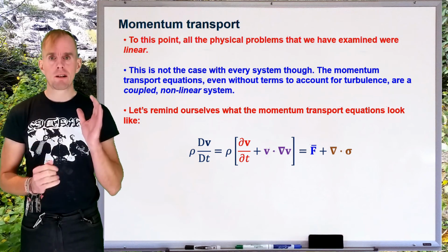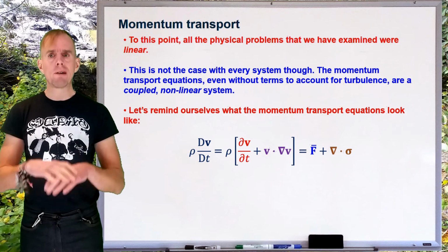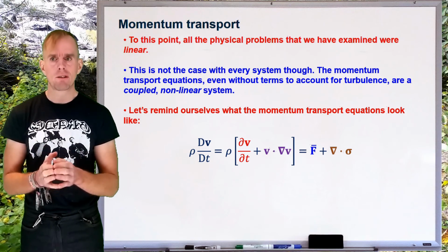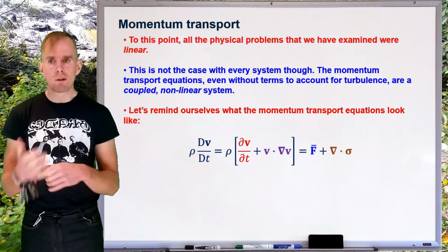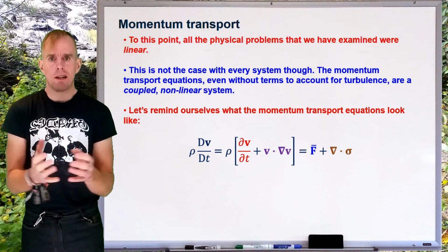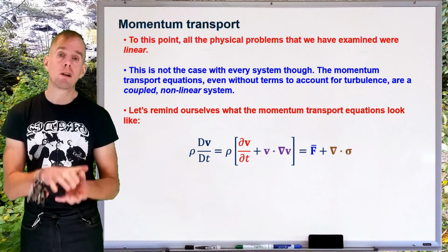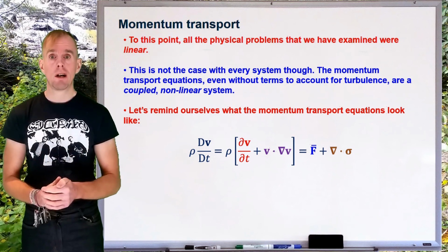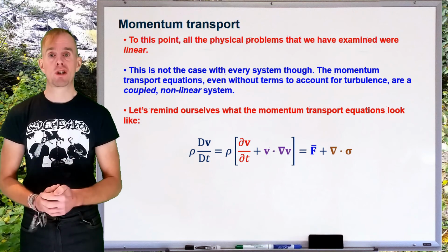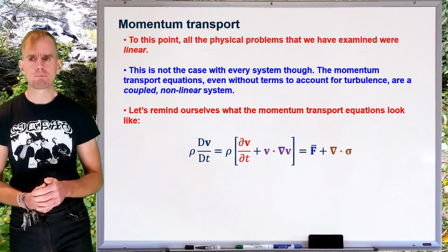And then we've got grad dot sigma. Now sigma here is something that I'm calling total stress. We'll have a look exactly what comprises this on the next slide. And we've got the divergence of that total stress giving us a force as well. And sigma here, therefore, are not the forces that act on the bulk of a material, but act on the surface of a material. They're surface forces. So they would be things like hydrostatic pressure, shear stress, elastic forces, and so on and so forth.